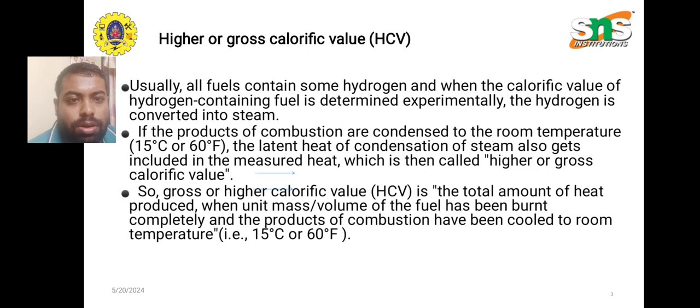So, gross or higher calorific value (HCV) is the total amount of heat produced when unit mass or volume of the fuel has been burnt completely and the products of combustion have been cooled to room temperature, that is 15 degrees Celsius or 60 degrees Fahrenheit.